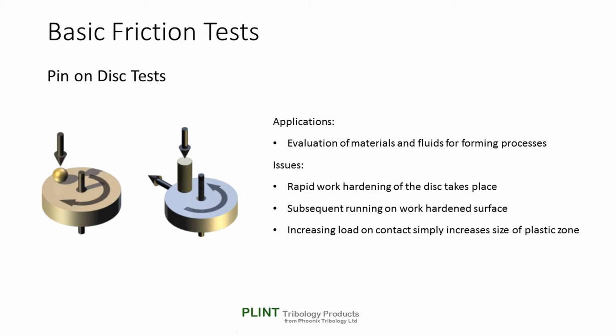The second point to note is that increasing the load on the contact simply increases the size of the plastic zone, making repeat tests at different loads somewhat pointless. Perhaps the only pin-on-disc type configuration that makes sense for modelling forming processes is indexing pin on disc, where the pin follows a spiral track, thus presenting fresh workpiece material to the tool pin. There is, of course, a limit to the distance available on a single disc.